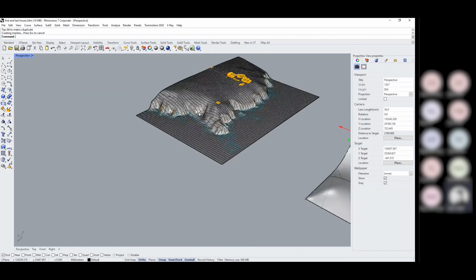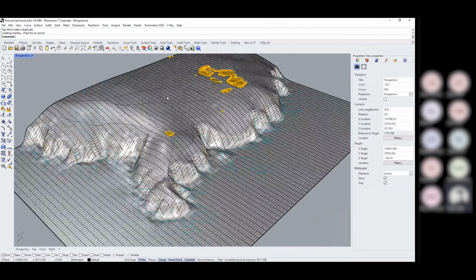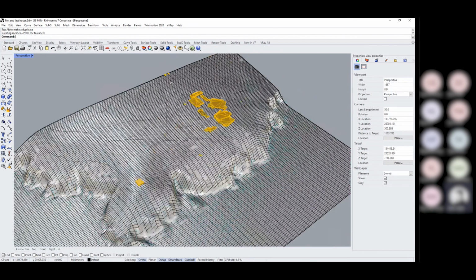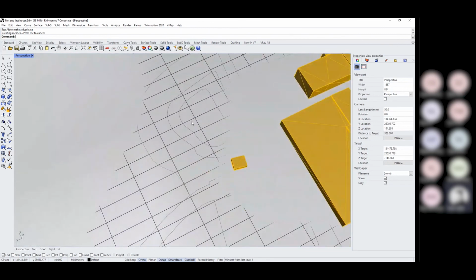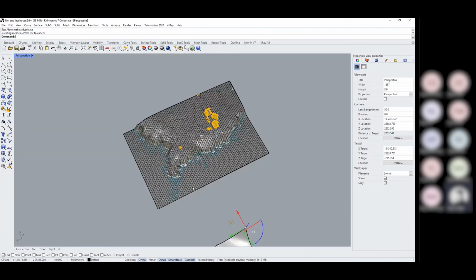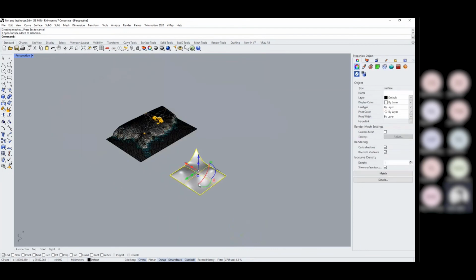Well, I could do the same thing with this one. If I'm using actual data, for instance, if I've generated a clean surface across it, I could project some curves. Maybe I want to work on this specific element here. I could use the split tool to split the surface from the rest, rebuild it, pull the points around. That means I can then start sculpting it and landscaping it. So again, pretty cool stuff.